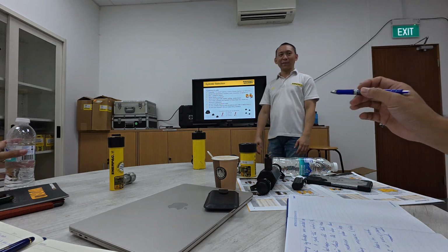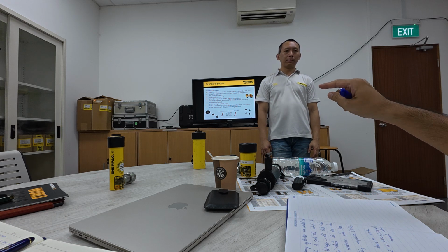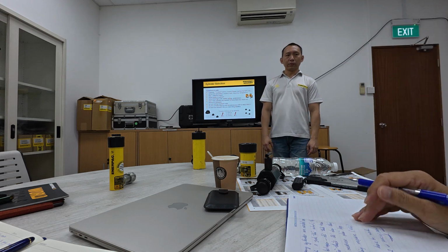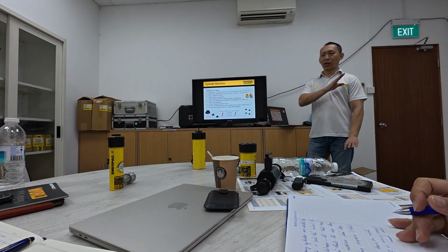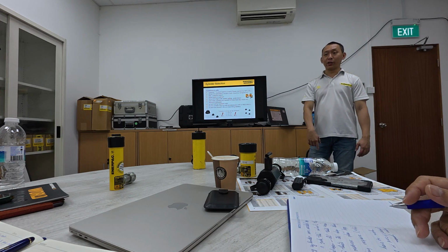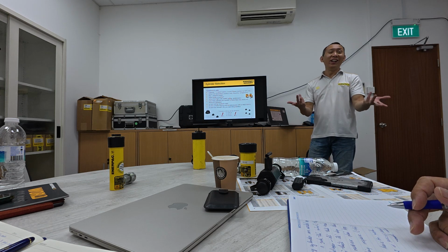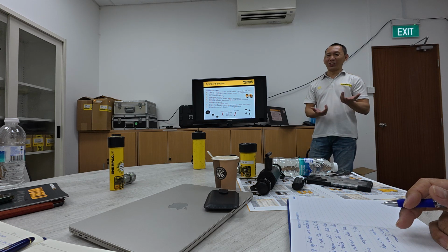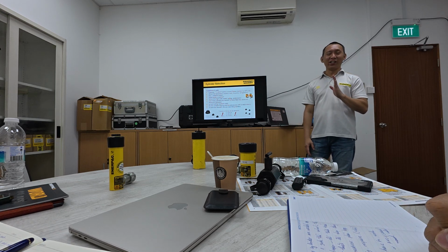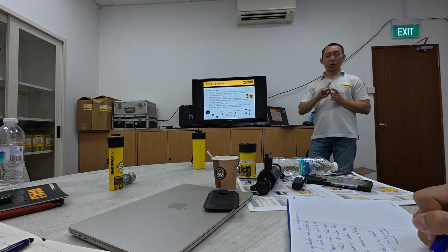So about 12% side load, does this appear in the specifications online? No, we never spec it there. We talk to the customer about zero. Just tell them don't accept any side load. Because if you tell them the cylinder can take side load and they side load it, then they say, why then do I have to claim warranty? You should not take side load. If they set up incorrectly and side loaded, it is their application fault, so it's not a warranty.